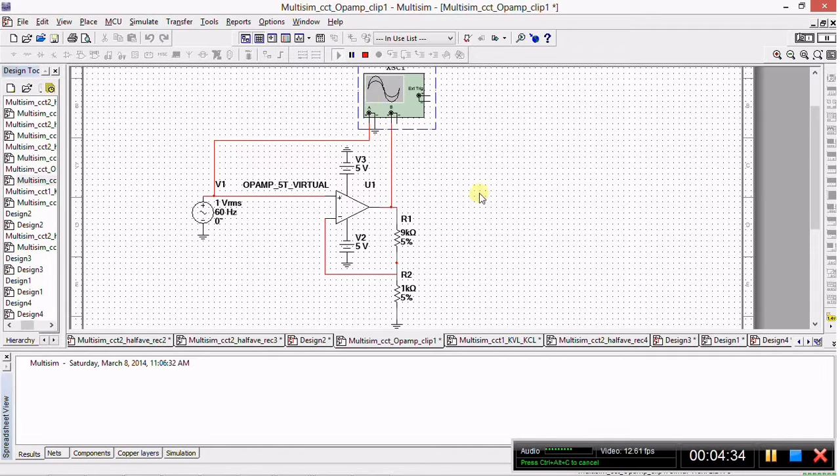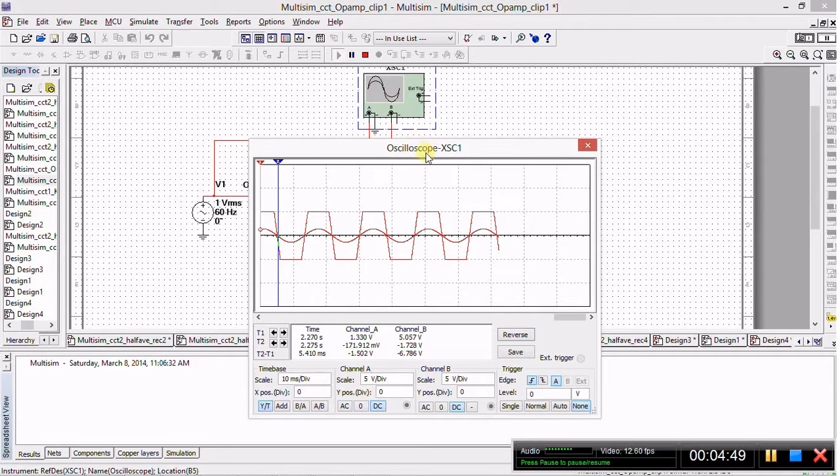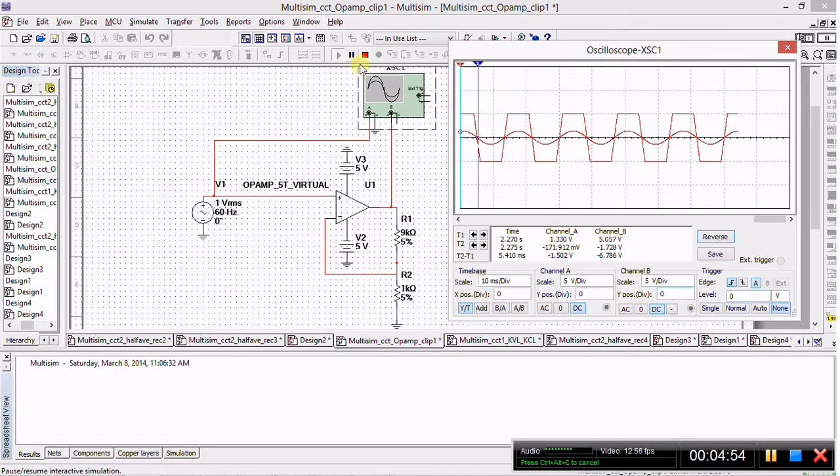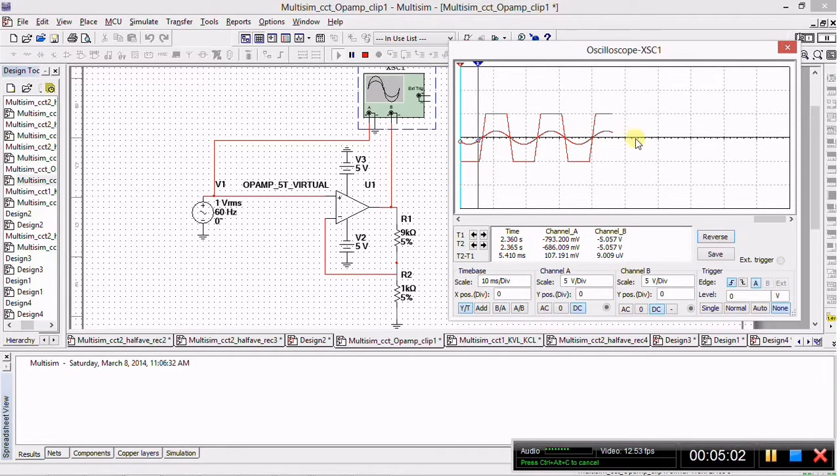Let's click play and simulate this waveform. Another thing to note are the locations of all the grounds. Ensure that you have all these ground locations before simulating the circuit, else you'll run into major issues. We'll bring up the oscilloscope screen as we had earlier, and there you can see the waveform being displayed. The trace at the bottom, the smaller sinusoidally varying one, is the input trace.